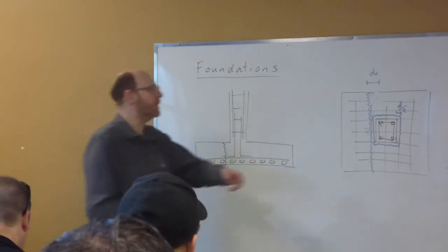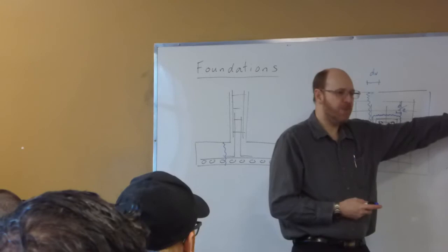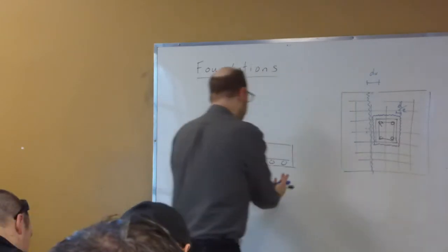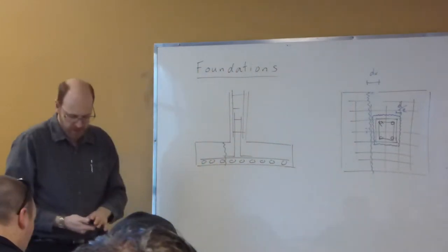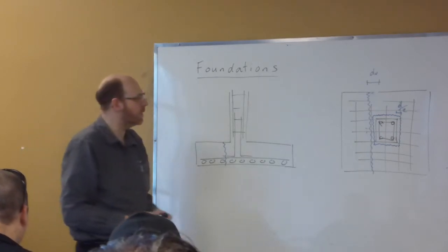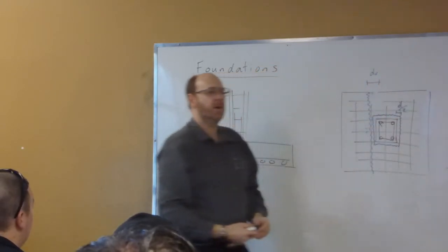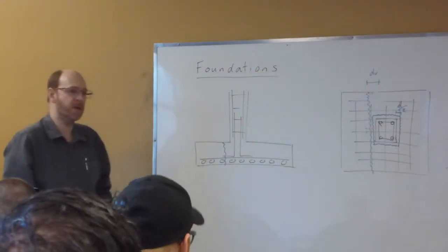So we have an initial calculation which gives us our area, right? And we work off of there to come up with our factored soil bearing pressure. This is what's actually pushing up from the bottom. We'll be using this as part of our shear calculation. And of course, our area is length times width. Right? And again, it could be rectangular.